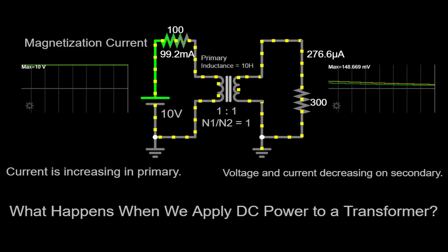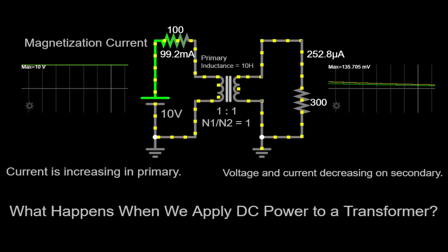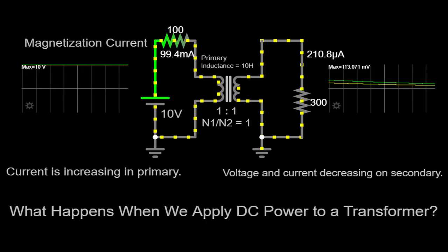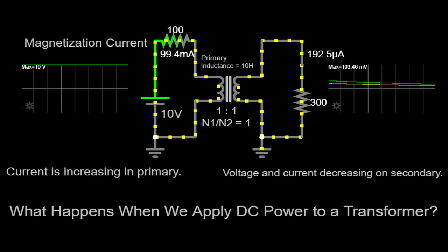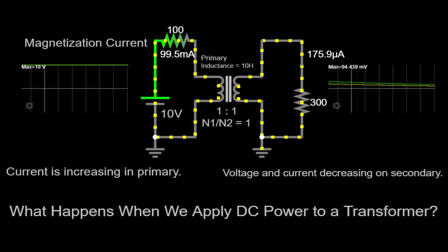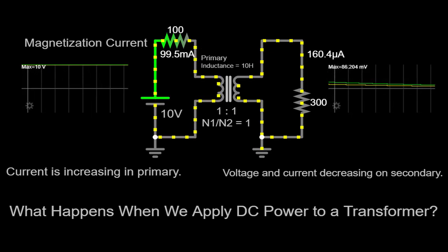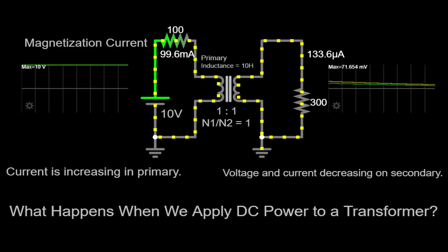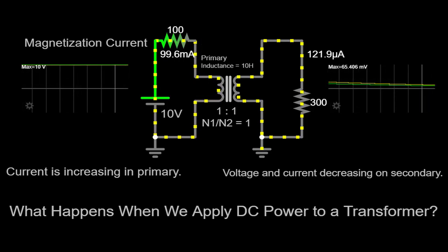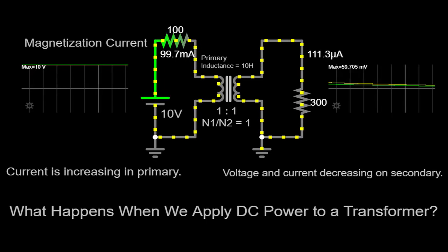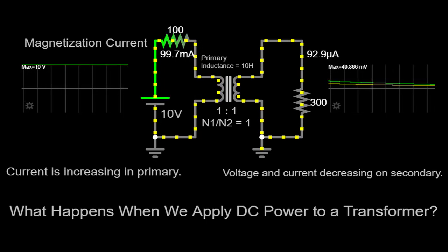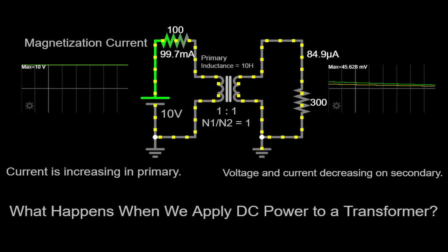In conclusion, it is of utmost importance to avoid applying DC to an isolation transformer, considering the multitude of adverse effects it can induce. These include the absence of voltage induction, core saturation, increased heat generation, and the loss of isolation and safety features. It is critical to utilize isolation transformers as intended, exclusively with AC inputs, to ensure optimal functionality and guarantee the safety of electrical systems.